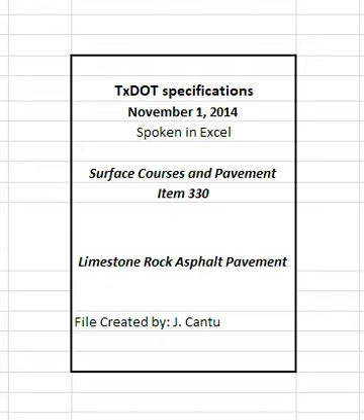Proceed toward the center of the pavement, overlapping on successive trips by at least 1 foot, unless otherwise directed. Make alternate trips of the roller slightly different in length. Begin rolling at the low side and progress toward the high side on super elevated curves unless otherwise directed.